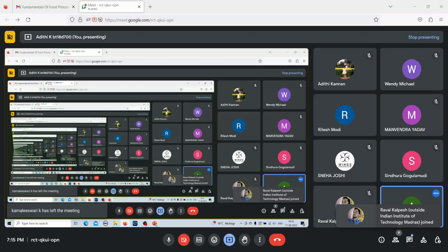Or the graphical method. We were solving the numerical method so far. The graphical method is basically you calculate the lethal rate L at each and every time point. You plot it with respect to time and you calculate the area under the curve. That area under the curve will give you F naught. That is also another way. But in order to simplify further, we are using the numerical method, which is F naught is equal to summation of L into delta T.